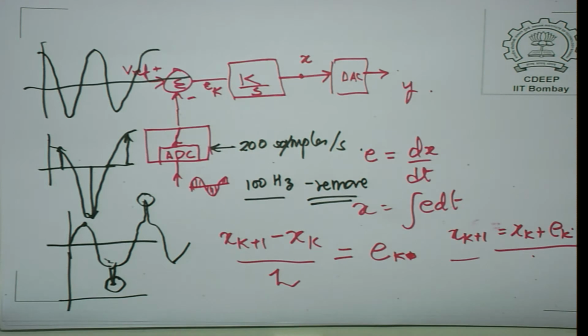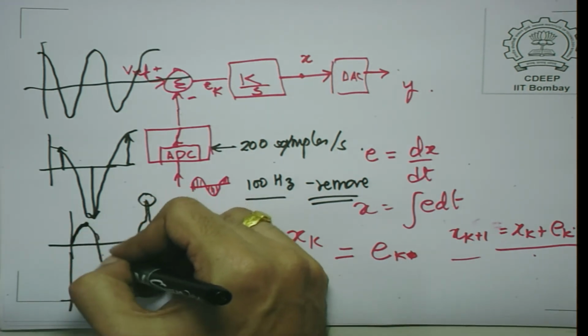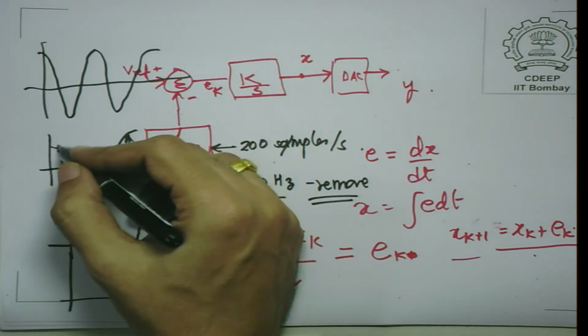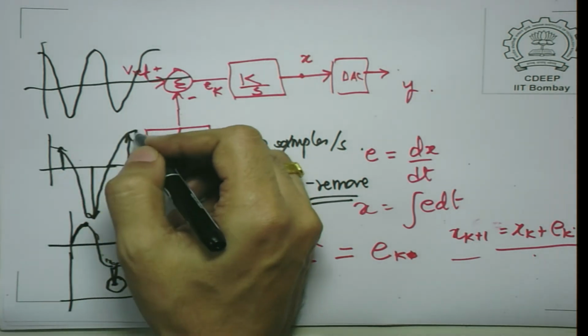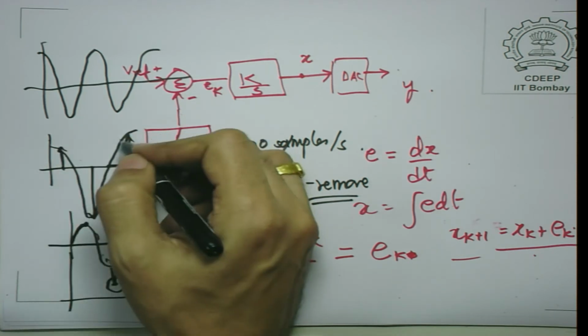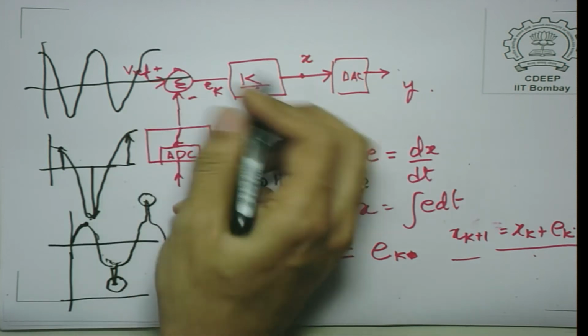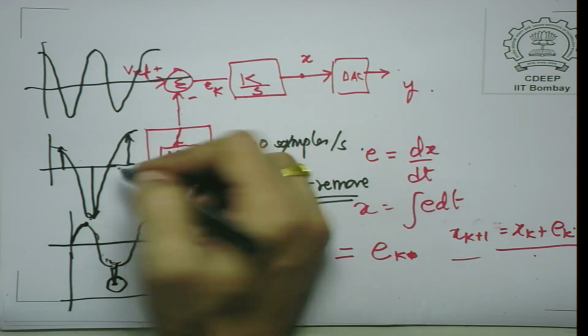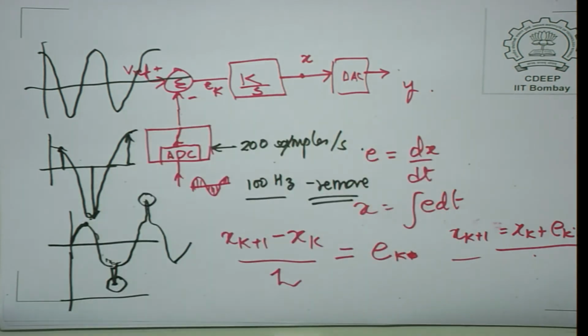So, instead of thinking of this as a signal with a few occasional spikes, if you actually sample the spike, you may assume that your waveform itself looks like this, because you have only these values inside the digital system, and you may infer what the waveform is just based on this, and you may get wrong inferences. So, this is a manifestation of aliasing. We have one simple question in your tutorial sheet which will try to bring out this aspect as well.